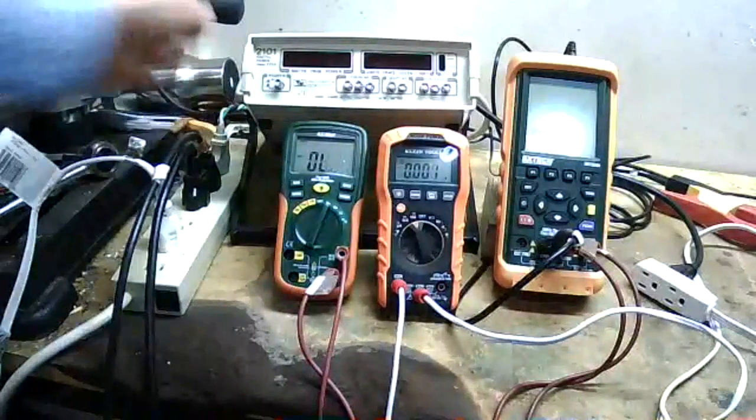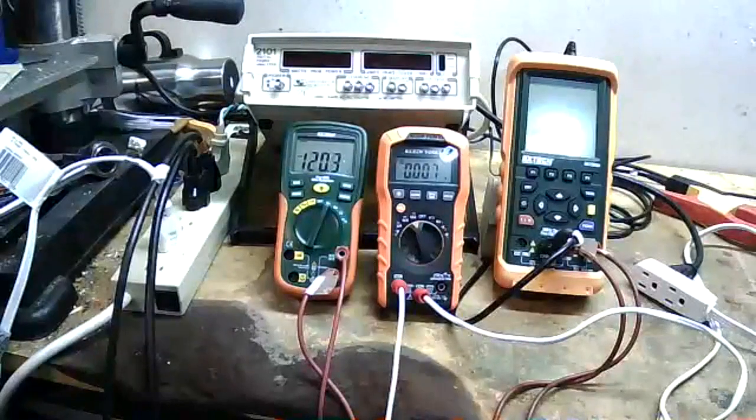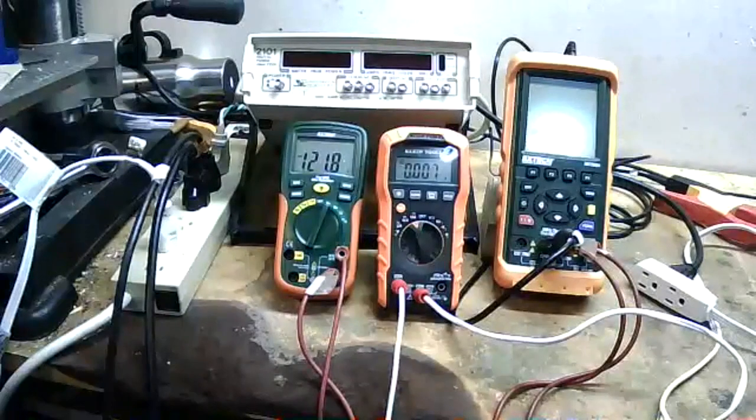So it appears we actually have some current flowing to the drill press while it is turned off, which is not an unusual thing. There is some leakage current in almost anything that's connected to the 120 volt system. So we have 7 milliamps flowing there, probably from capacitive coupling inside the machine itself. We could track that down if we needed to. It's not a concern here.